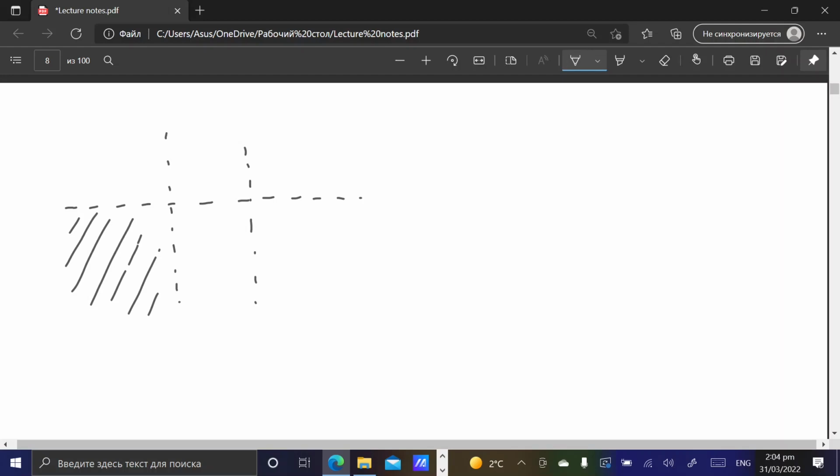So that means that all these processes are happening in the quite thin layer next to the interface. Deeper in the bulk of the semiconductor, nothing is going on. So we actually have here just the so-called neutral region as it was before. We have EC. This is our Fermi energy, and this is our valence band. So as we had it before the contact, the same we have here.